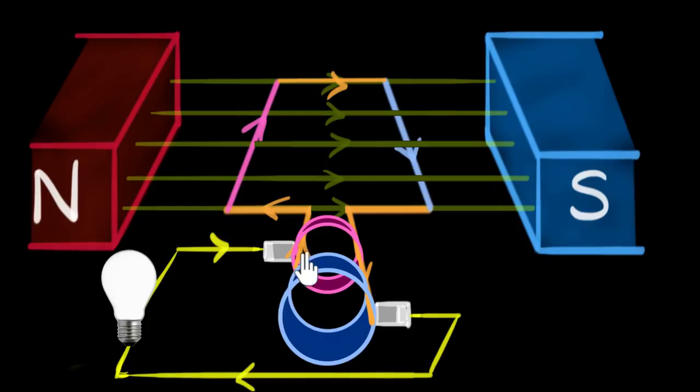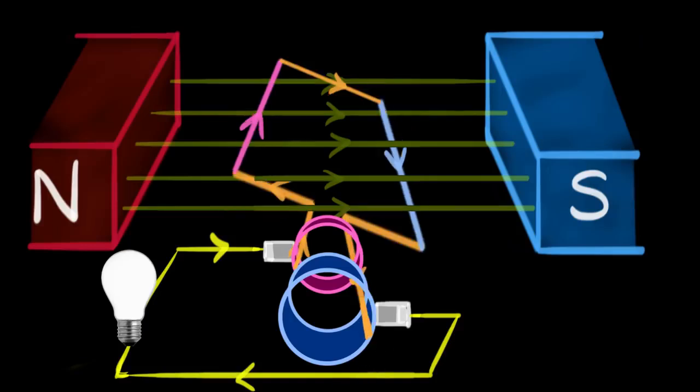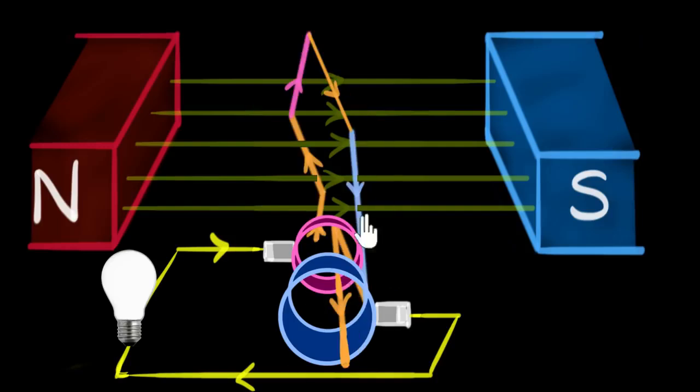So right now, there is a contact, the circuit is complete, and as a result, the current comes out of the blue ring, as you can see, moves this way, and current flows into the pink ring and goes like this. And when the coil starts rotating, as you can see, the rings rotate along with the coil. But since the brushes are not stuck to the rings, the rings just slip through the brushes. That's why they're called slip rings. As a result, the brushes will not rotate. That solves the problem of wires twisting and tangling. And all the while, an electric contact is maintained.